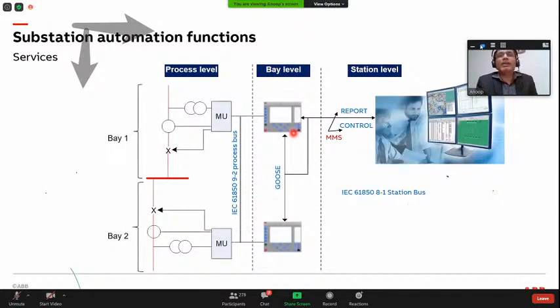So I'm bringing the previous picture again here, which you might have seen, process plus GOOSE, and I'm going to talk specifically about the report part. For example, how data from a bay level device, the IED, is sent to the SCADA, so that I can see the temperature is correct or not, or your current is flowing correctly or not. This is something which I'm going to explain.